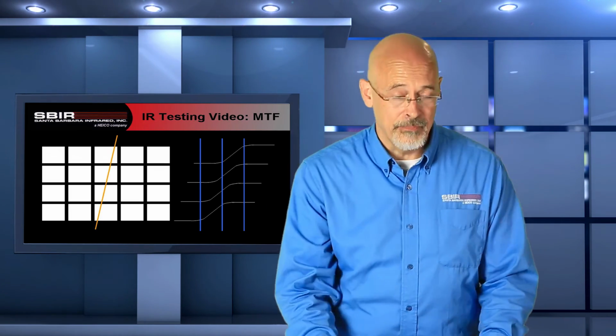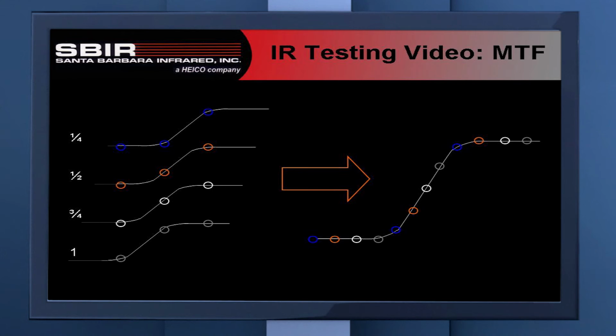So how do we deal with this problem? Well, as you can see here, we have the Nyquist limit of our signal, and we have an MTF to the left of the Nyquist limit. That's our measurement. All the frequencies at a higher rate produce a curve that's going to get actually mapped back onto the Nyquist, onto the MTF curve, so that all those images or those frequencies affect or impact our lower frequency measurement.